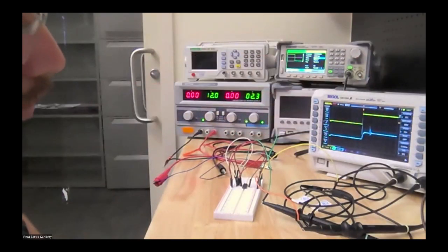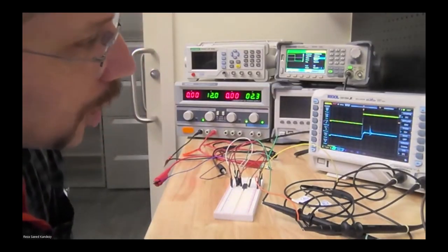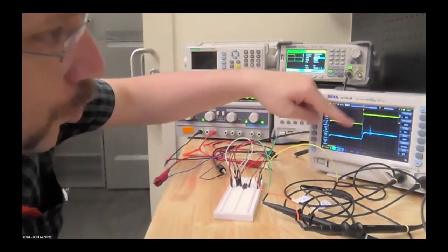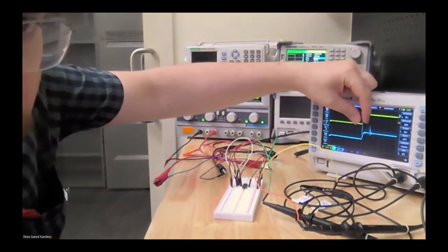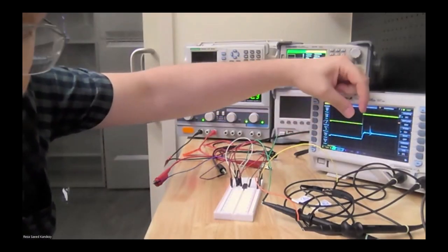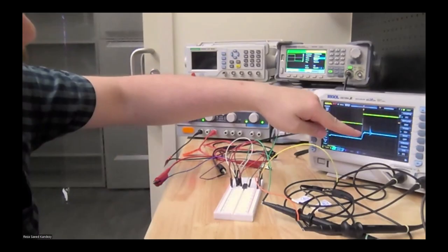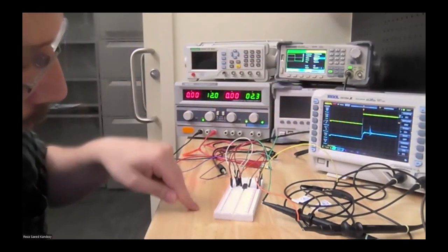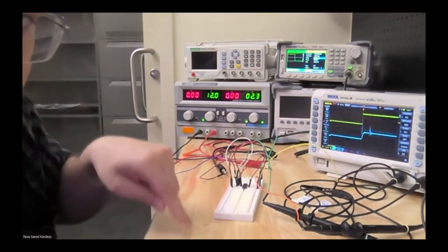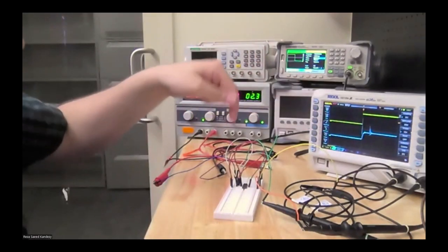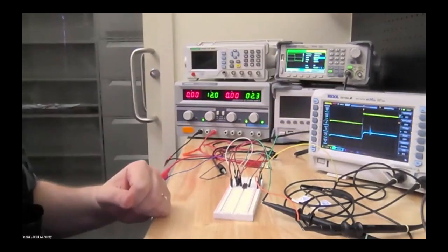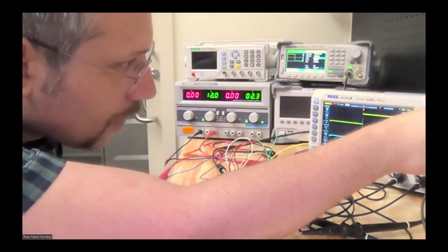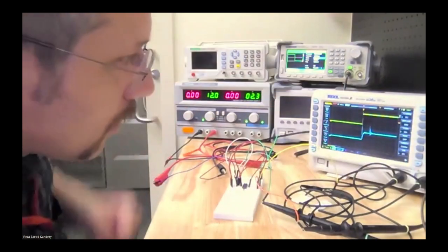Okay, now if I wanted to count, I could count two lines within 1 unit. It's like 40% of 1 unit of the grid, and each unit based on my setting was 5 microseconds. So 40% of that 5 microseconds becomes 2 microseconds. So in this example, it takes 2 microseconds for the voltage to go from 0 to the final value.